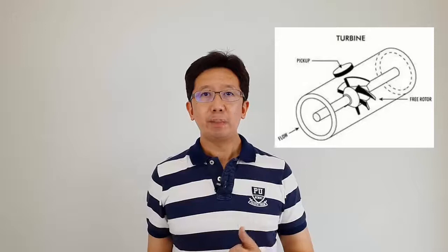The turbine flow meter is one of the most accurate meters for low to medium viscosity products due to its insertion design, and turbine meters also provide a very fast speed response. The limitation of the turbine is that it is incompatible with high viscosity or dirty liquid, and it is potentially damaged when contacting two-phase flow or debris metal. So, an inlet filter is required.